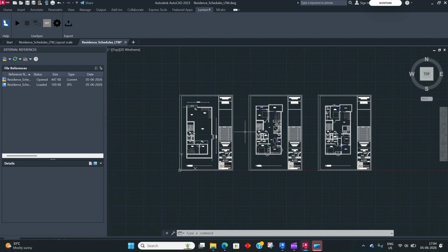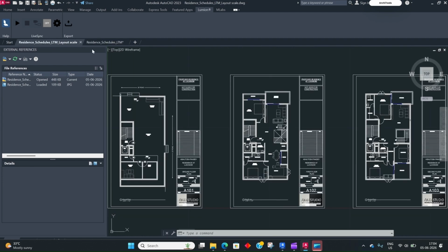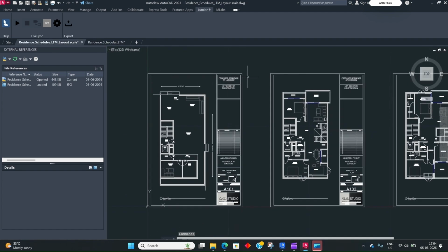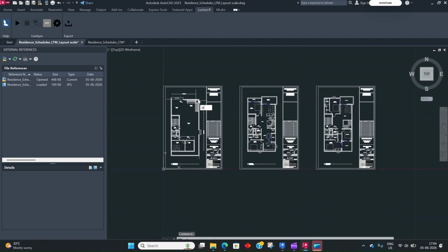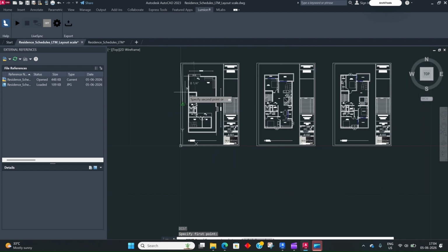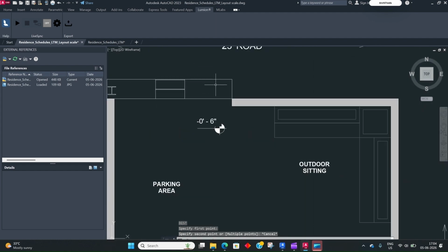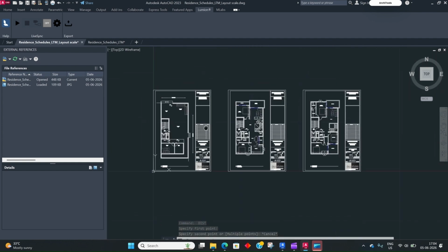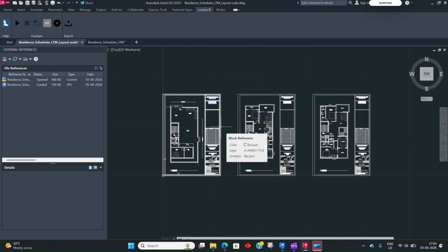So this is one of the ways of doing it, and the other is you're keeping the layout size fixed. So in that case, if you take the dimension of the sheet, it would appear as per the layout, but if you take the dimension of the views inside, it will be lower. So these are two ways. You can choose any way which is more preferable to you, and you can export multiple views in a single CAD format.